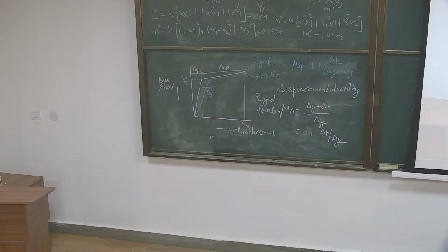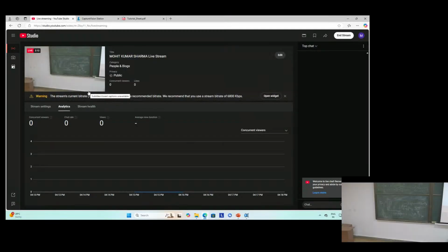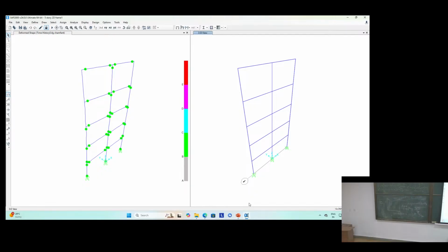Okay, so you are ready? Everybody is ready? So this problem, what is there? This is a typical example which we have generated for all of you. In which you have a slab depth of 150 mm. The imposed load is given as 5 kilonewton, that is your highest live load in any structure. And column size is defined, 450 by 450. Concrete grade and steel grade, material grades are given to you. Base size is given, and it is a 5-story building.